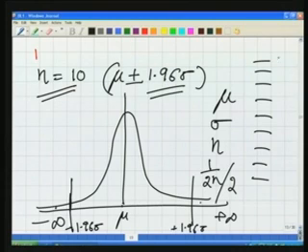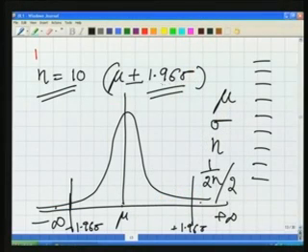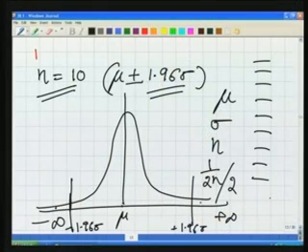So, in your set of observations, now you can find 1.96 sigma, whatever it is, you know it. So start looking, are there any values which are less than mu minus 1.96 sigma, or more than mu plus 1.96 sigma? If it is so, reject them. The only thing is, we do this exercise only once, not in iteration. Just only once we do it, we reject the observations, and that's it.